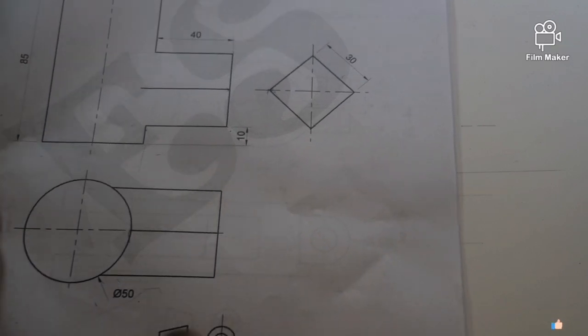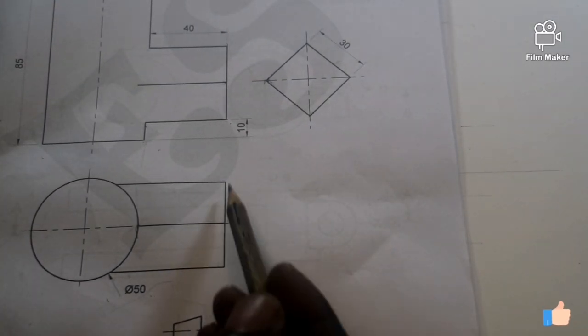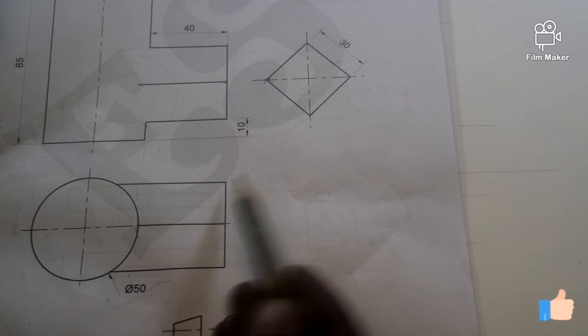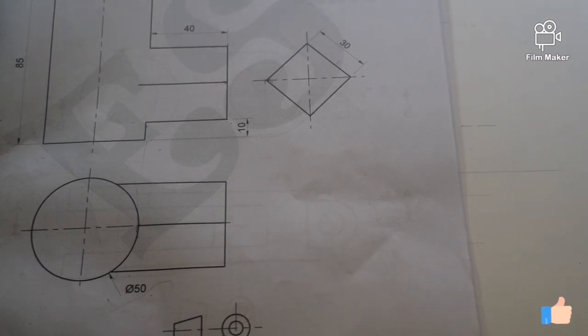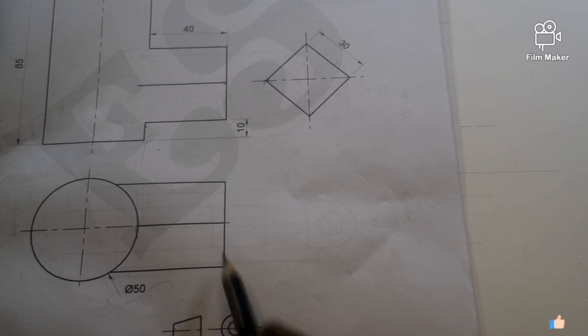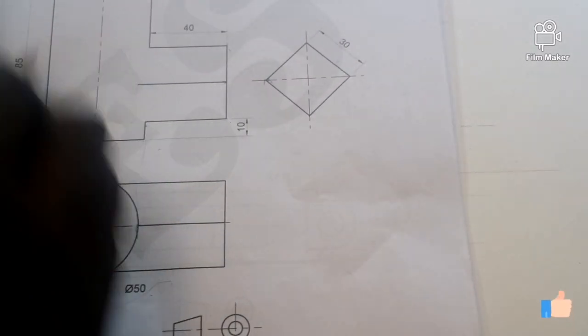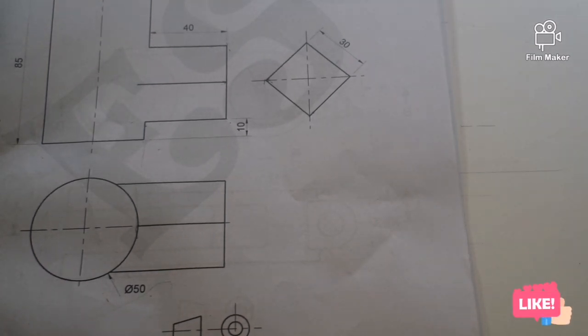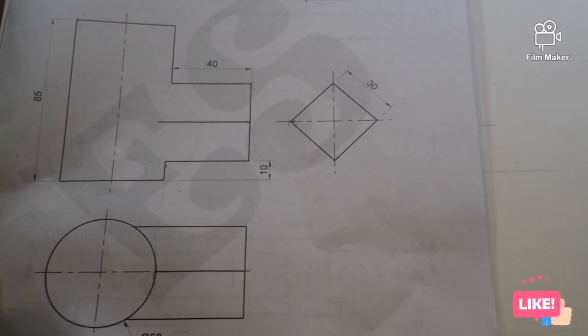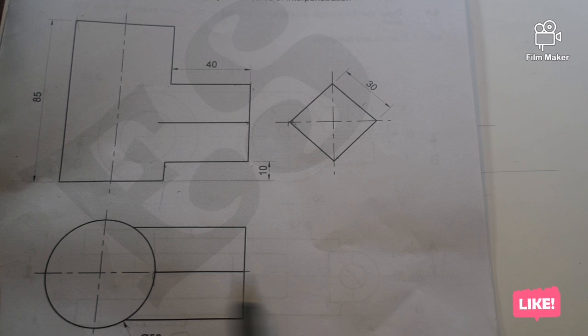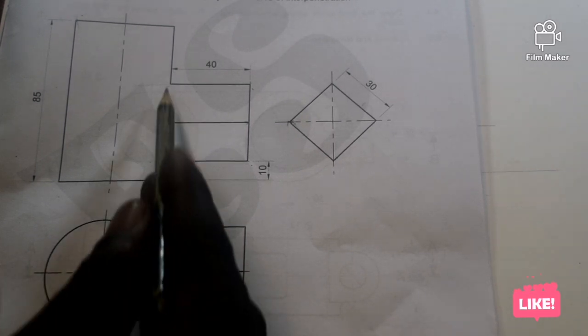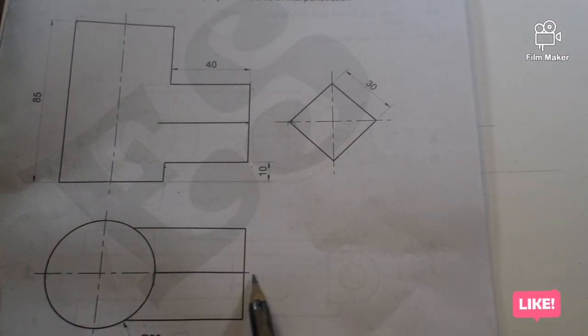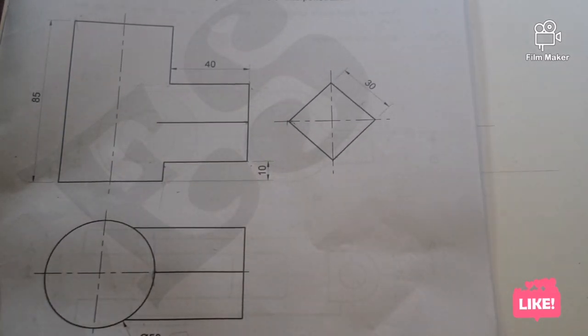And if you look there by our top view, we are not given the breadth, because in the top view we do not have height, we only have the length and the width or breadth, you understand? So from here till there is the width, from here till there is the height, which is the front view, isn't it? The front view and the top view will always share the same length. Which means if from here till there is 40, then from there till there is supposed to be the very same 40, isn't it?